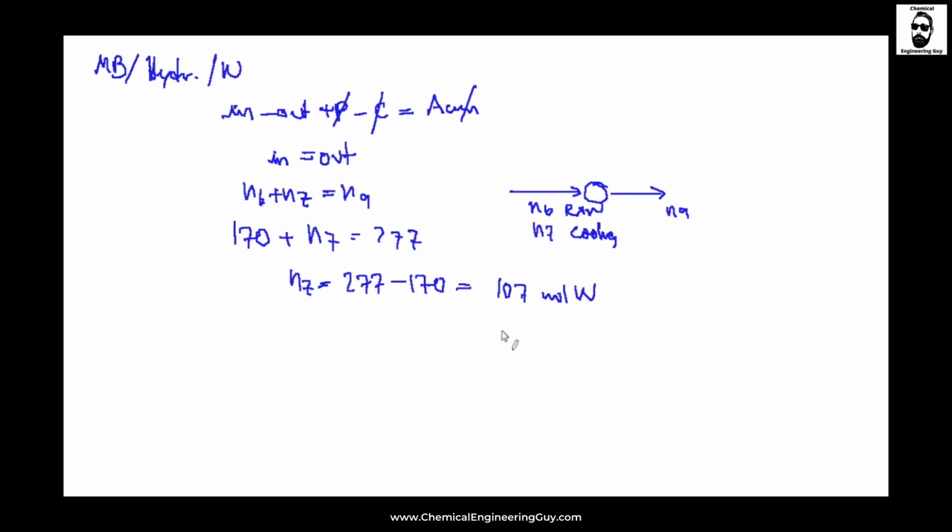And they want it in volumetric flow, and since it's a liquid, please don't use the ideal gas law, use densities and mass relationships. I know that the volume equals the mass flow divided by the density. And I don't have mass flow, I have moles, so how do I relate that with molecular weight, of course?